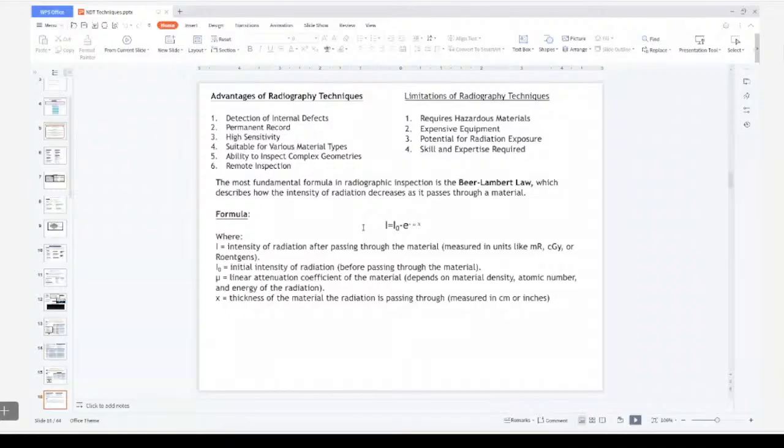So in order to reduce the difference of the impedance, people use immersion testing, like in water, because air has a high impedance difference. It means a lot of scattering will be there in the ultrasounds. So when I use water, the scattering can be minimized. Let's say I send about 100% of ultrasounds, at least 90% intensity will get into the sample if I use water. If I use only air, about 50 to 70% will get scattered, and only 30% of the energy will get into the sample.